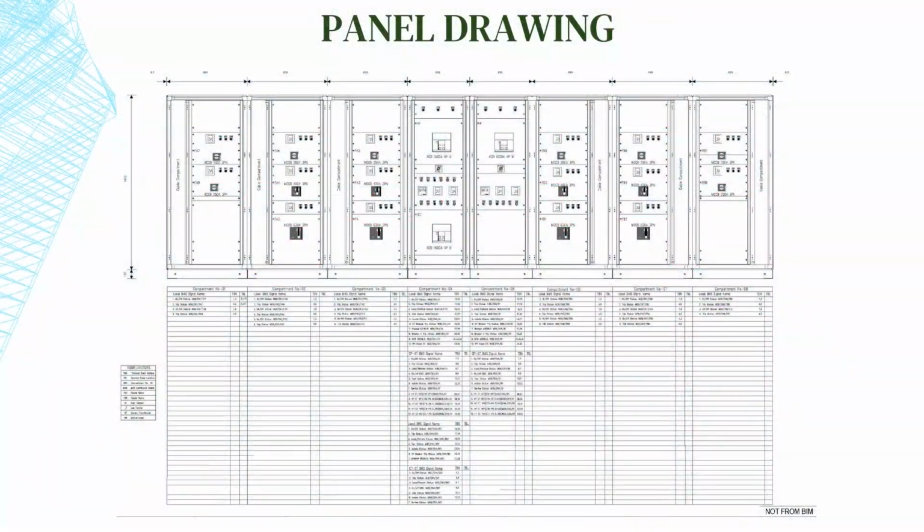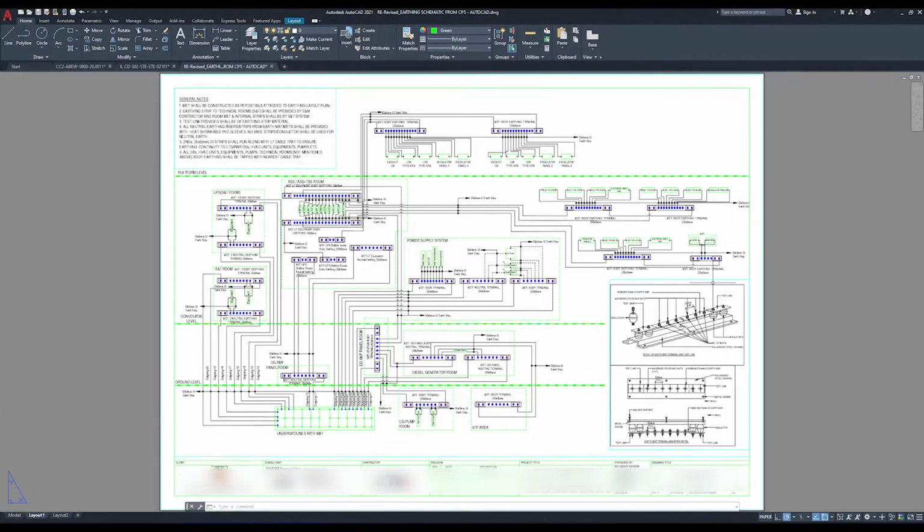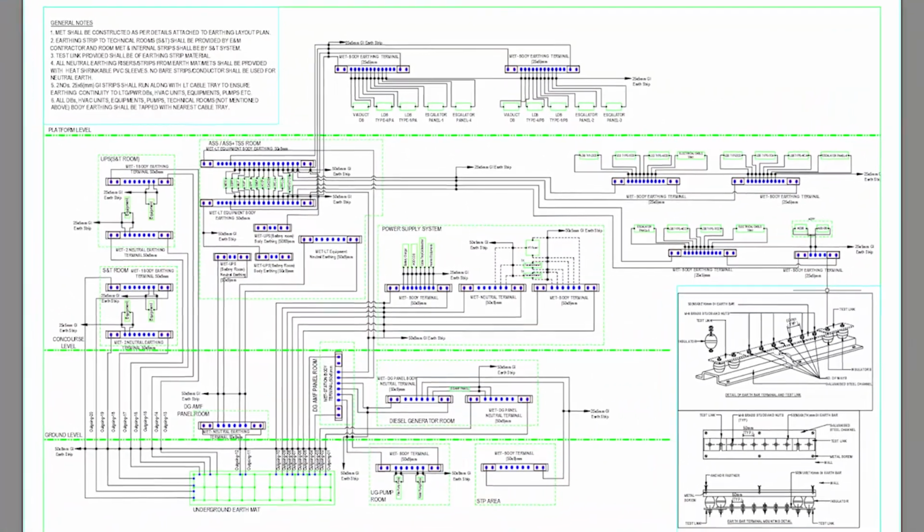This is a general arrangement drawing of a panel which was prepared using the OEM's own software. This is actually ABB System Pro E panel which supports 4B segregation as per IEC 61439. I have also done the protective earthing and lightning protection design.